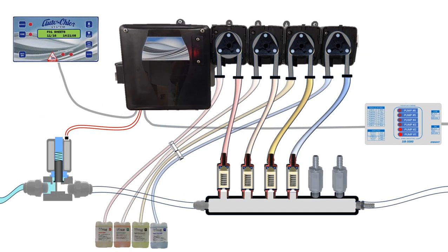When the dispenser receives this information, it's going to activate the pumps that are required, and it's going to dispense its chemicals. Check valves open up, dispenses into the manifold. The flush solenoid valve will automatically turn on based on its programming and flush the chemical to the washers. Once the appropriate amount of chemicals has been dispensed, the flush solenoid will continue to flush the lines to clear them going into the washing machine. When the flush solenoid closes, it shuts off the water supply to the manifold.